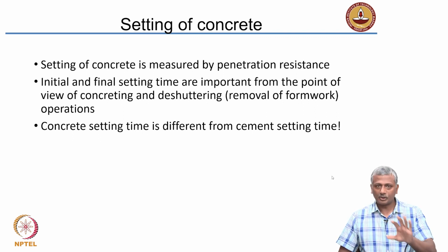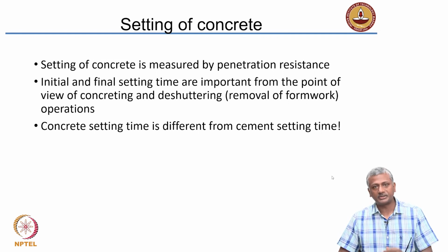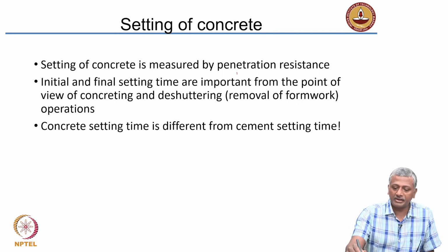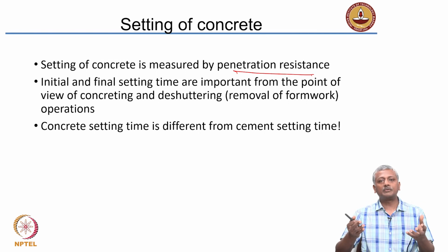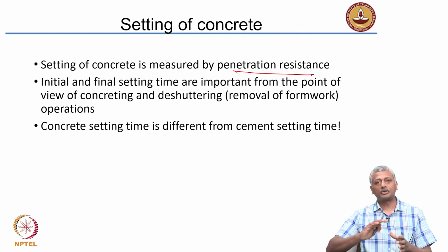Now, of course, concrete also sets because the cement is hydrating and gaining strength, but the setting time of the concrete may not be exactly the same as the setting time of the cement. Okay, so you need to actually measure the setting time of the concrete. Typically, that is measured by a process called penetration resistance. Now, this generally involves that you take the fresh concrete and sieve it through a 4.75 mm sieve so that you remove the coarse aggregate, and you collect the mortar.